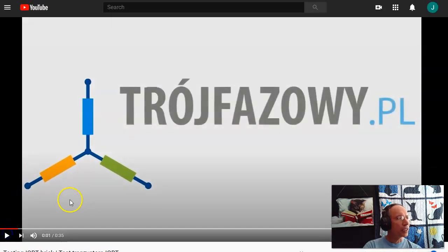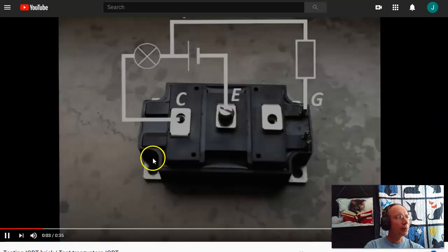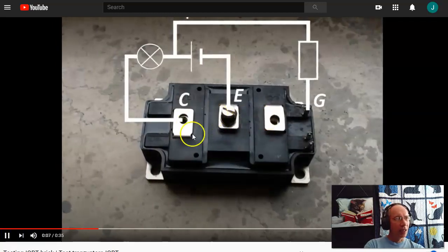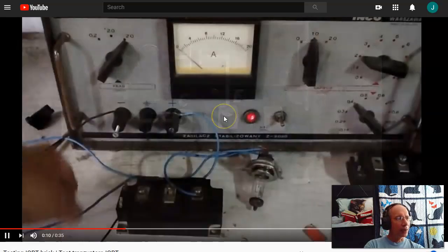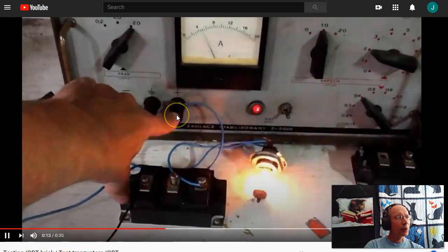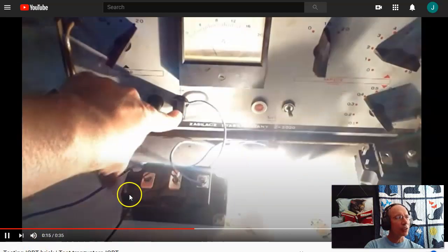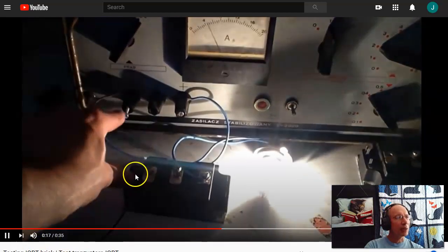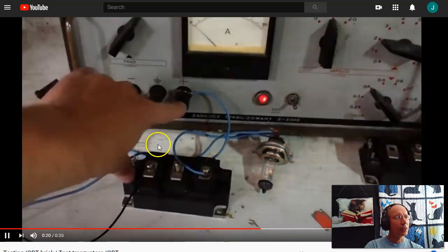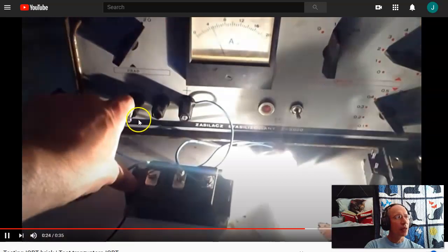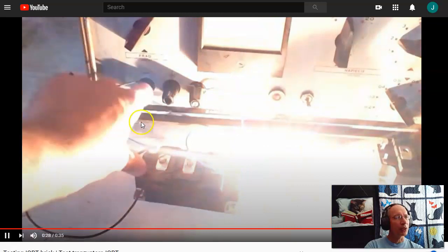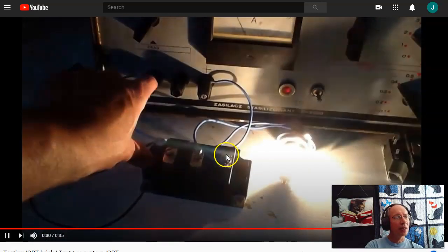This is a semiconductor relay. And you've got the gate, and then the cathode and anode. Notice initially there's no current flow. What he's doing is he's touching his finger to plus 5 volts and the gate. That allows a little bit of current flow that turns on the thyristor. Once it turns on, it stays on. He then touches ground. Ground turns off the NPN, which turns off the PNP. That's the idea of a thyristor.